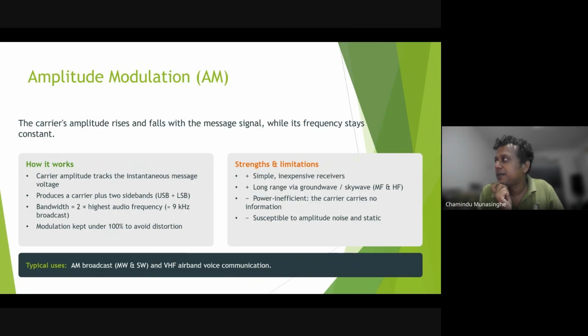Even if two people transmit at the same time, in FM the stronger signal takes precedence and drowns out the other station. But in AM, you can even hear both stations. The weaker one will be weaker, but you can hear both. So AM is a safer alternative for airband communication because of that, and other historical reasons as well.